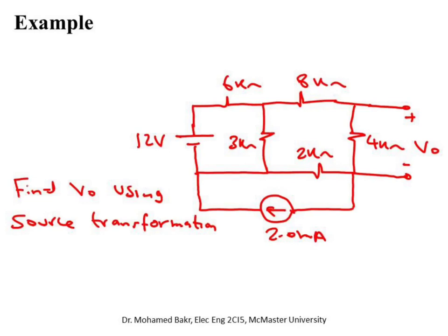You can have nodal analysis, so one node, second node, a third node, maybe take this one as ground. You can do superposition. First use this source and then use this source, and then you sum the 2 V outputs. So these are all possible techniques, and I encourage you to try this example using these techniques. What I'm going to be using is simplification using source transformation.